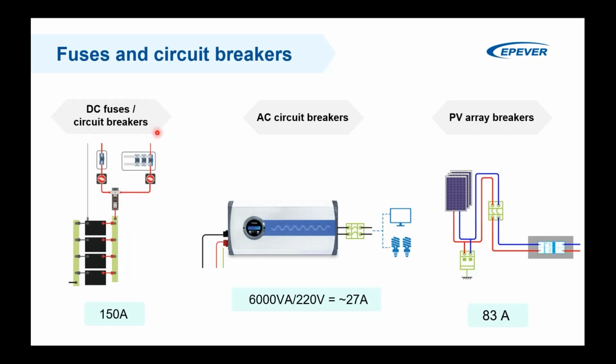Then I know that the fault happened here. But if you do not have individual fuses, you never know what happened, or you at least have to spend some time to troubleshoot and diagnose your system to find the fault. So it's always good to independently connect all the consumers with a dedicated fuse to the batteries for troubleshooting purposes.